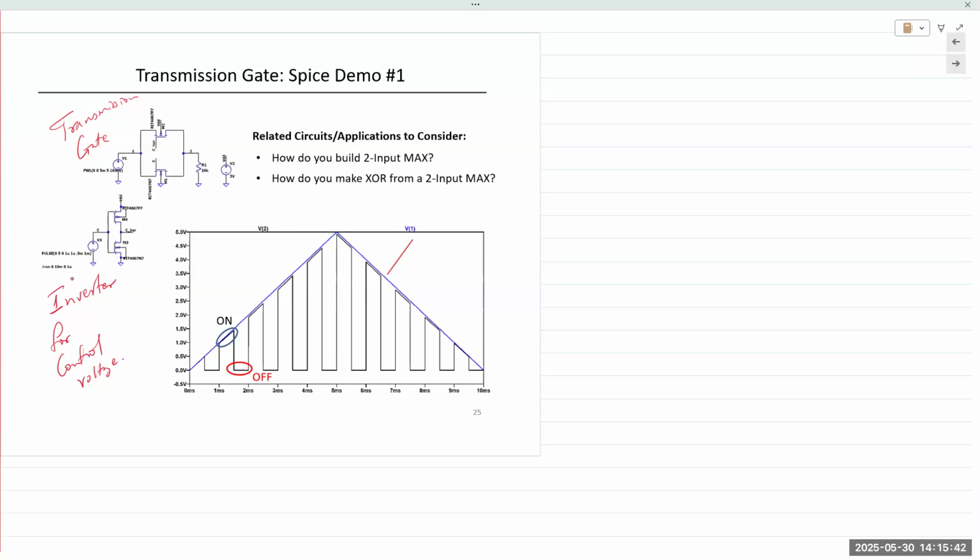In this case, we are ramping the input V1 up from 0 to 5 volts and back down to 0. And we are applying a rectangular pulse waveform as the input of the control inverter. So when the input arrives, it turns on the transmission gate, and we obtain the output. And when it's off, 0 output. So the circuit tracks the input coming to the control voltage inputs.